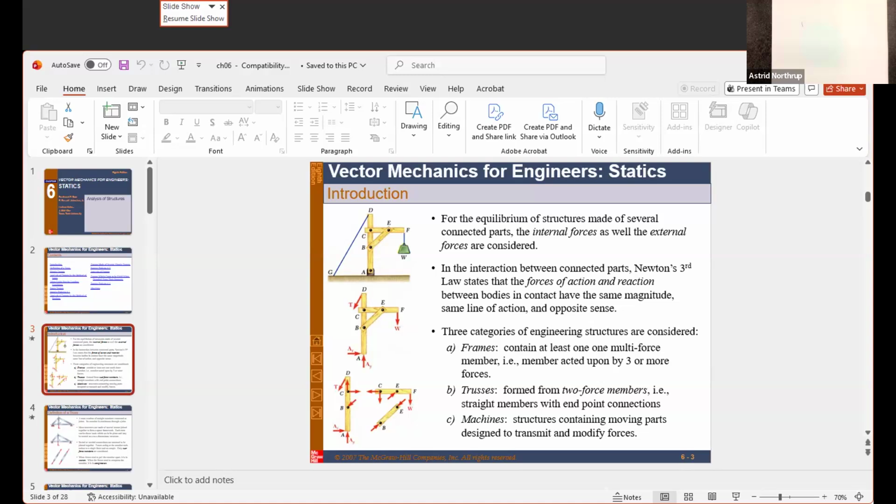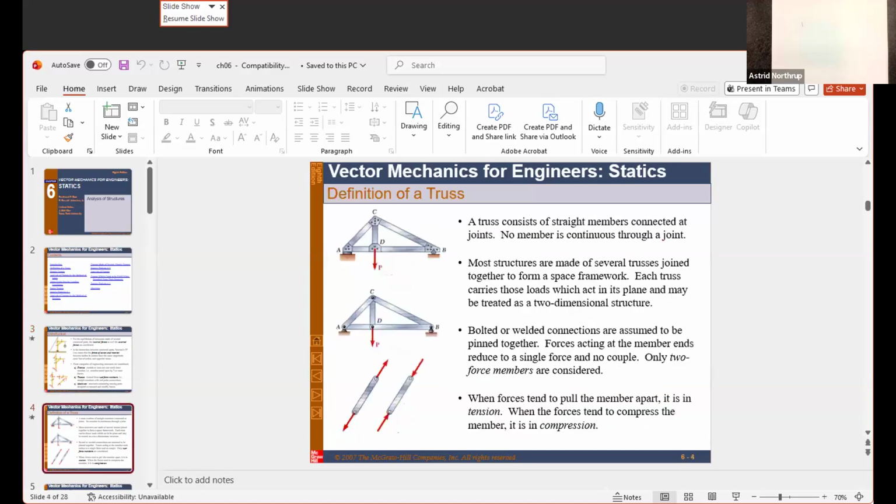I'm wondering why there isn't an A sub X in this diagram, because I don't see any X forces. That cable is X and Y both. Yeah. So think about removing that cable. If this is a pin, what's going to happen at A? Right? So there must be something going on there. And here's the good news. If there isn't something going on there, it will be zero in your calculations. So that's the only time you have to really worry about that is if you have too many unknowns to solve for. But very good questions.